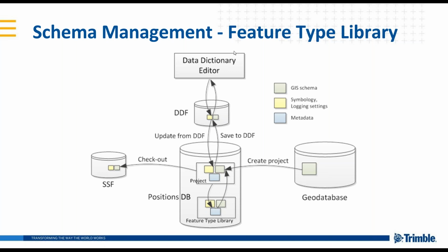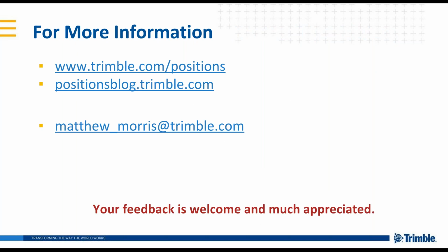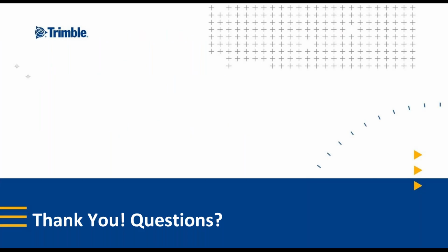You can still take it out to the field and edit it, out to the data dictionary and edit it, but you need to be aware of what's going on behind the scenes, such that you're not trying to edit schema in the data dictionary editor. The master schema is what resides in your geodatabase, and if you do update the geodatabase schema, you need to be aware of this when you want to propagate that change out to the DDF or out to future SSFs and checkouts.